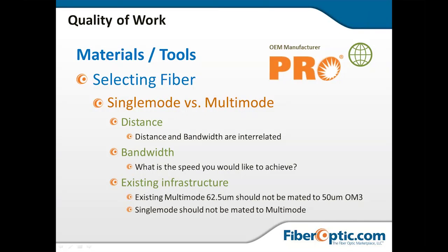I really don't understand the value of multi-mode in any applications any longer. For a long time, it made some sense because the transmitters and receivers for single mode fiber were much higher in cost.